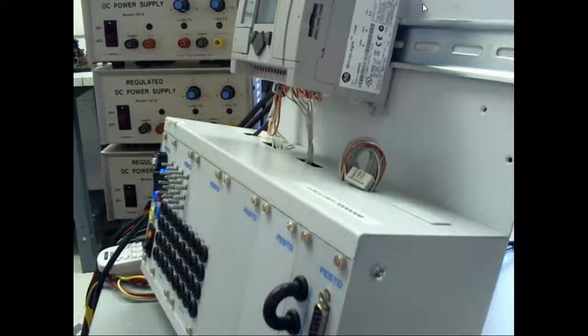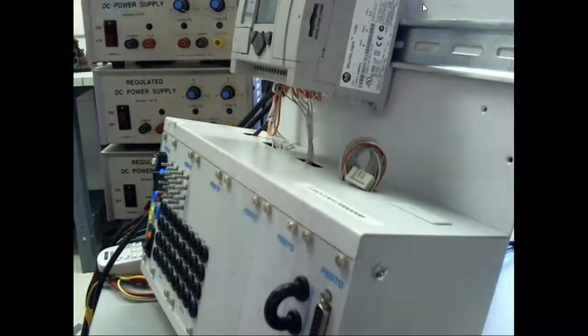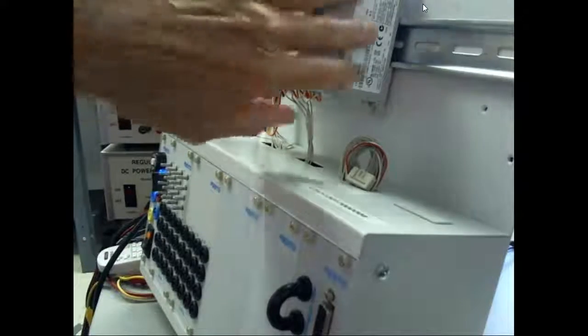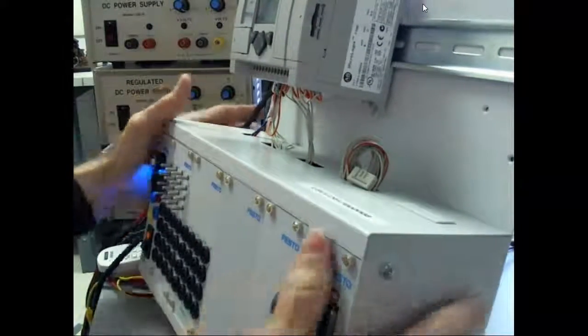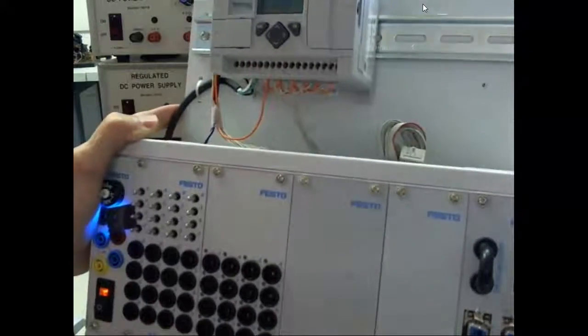Some of y'all will be on the Micrologic 1000, which are fixed PLCs, and it's going to be great for this class. And then some of y'all will be on the 1100s, which I call hybrid PLCs. Some people still call them modular. But what I want to tell you is it's a fixed PLC, but you do have the ability to expand it. You just pop this cover off, and then you can put a memory card in here, and it mounts on this guy called a DIN rail, and it just snaps on. Y'all can't see those tabs on the bottom. So all I'd have to do is put a screwdriver in here on the bottom and pop these tabs down. I could pull that PLC off.